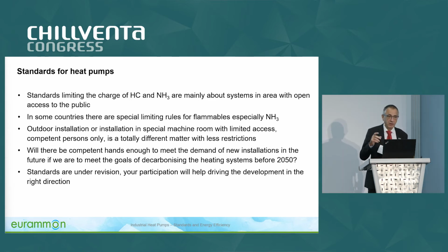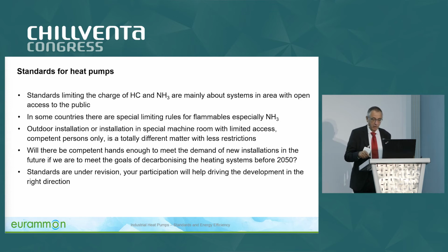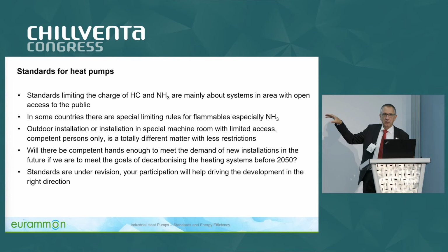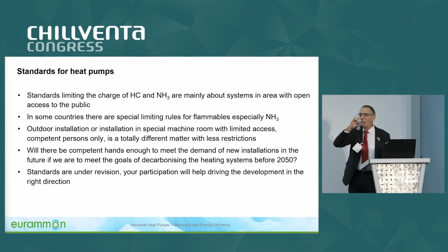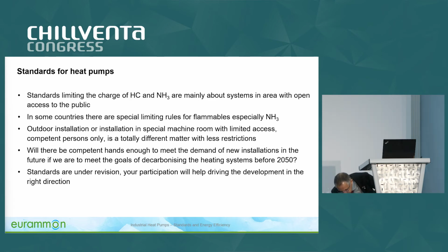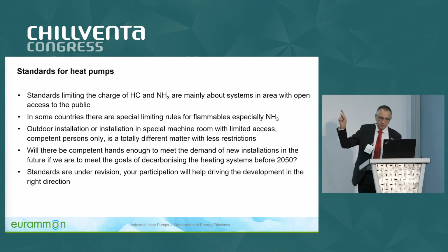And the 150 grams that Tommy was talking about earlier is now lifted to 500 in the ISO standard, and it is for indoor systems only. When we talk about outdoor systems like heat pumps, there is no limit to how much refrigerant we can have on board the chiller or heat pump. So that is a very important thing to get clear.